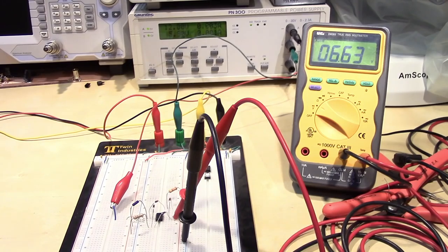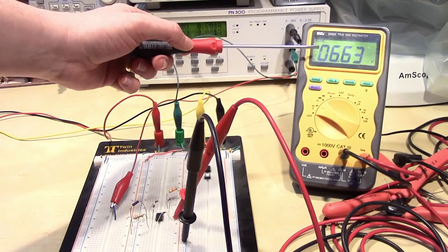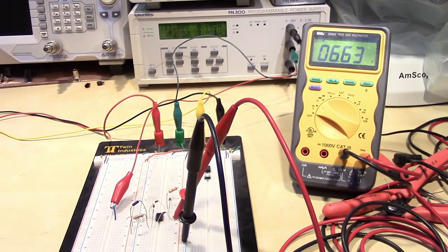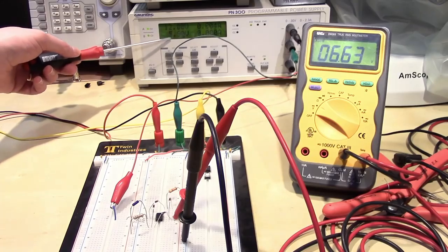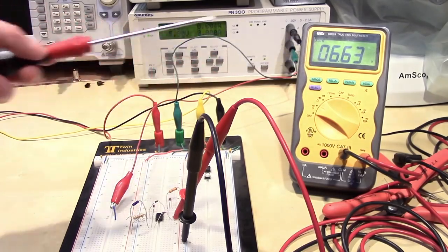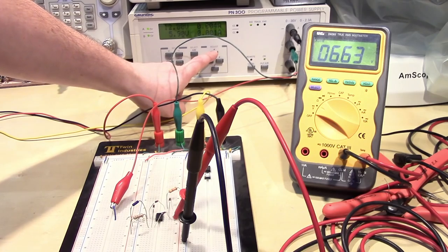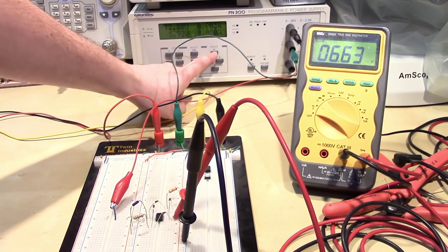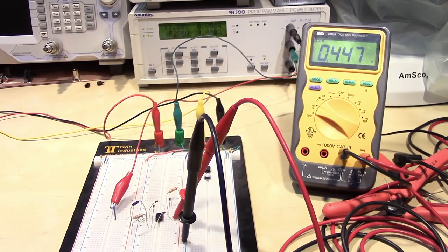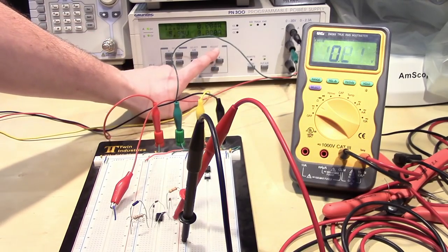So I've got this circuit built up on the bench. I'm measuring the output of the op-amp with my multimeter here. You can see it's currently driving its output high, and I'm inputting a voltage of 5.9 volts. So the high output voltage shows that we are below the low threshold voltage of 6 volts, which we certainly are at 5.9 volts here. So I'm going to increment my voltage here to 5.91, 92, 93, 94, 95, 96. Oh, there we dropped down to pretty close there to 0 volts, about half a volt. So the trip voltage here is 5.96 volts.